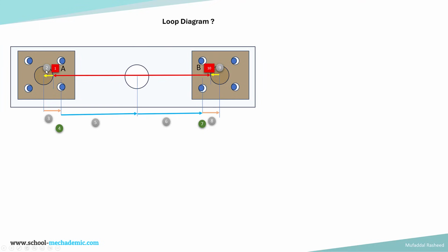Second type of variation, which is the second specification, is the variation in the diameter of the post. So that we can take directly from the drawing of the post. The diameter of the post varies and that variation is captured here. Now we go towards the right. So from the center axis of the post, we go towards the location of the hole.